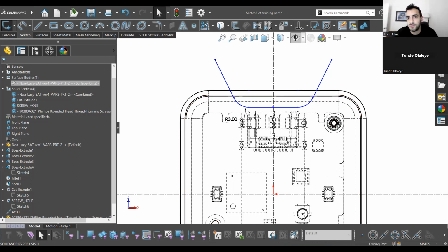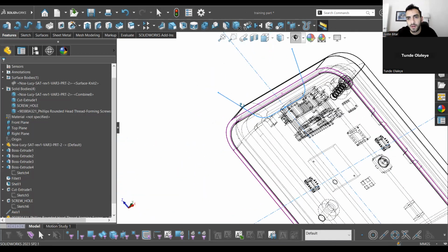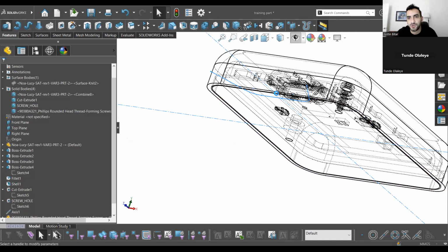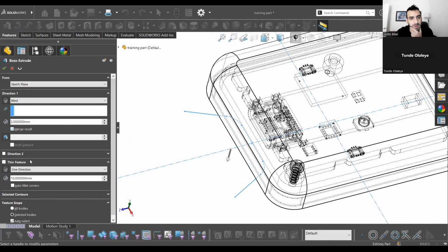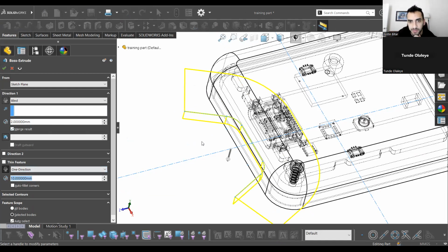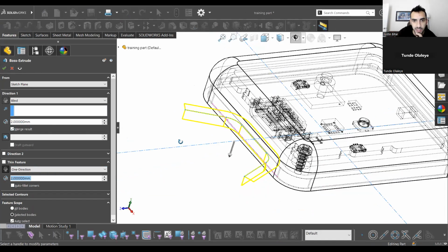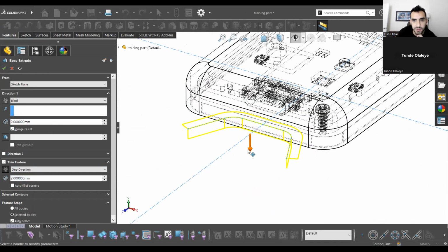Let's try it like this. Let's try this real quick. I'm going to actually extrude this line, right? And so here we're going to get a thin feature, right? It'll say, hey, this will just be a thin feature, and it'll give it a default width of like 10 millimeters. Actually, we know we need this to be 2 millimeters thick. The wall thickness needs to be 2 millimeters.